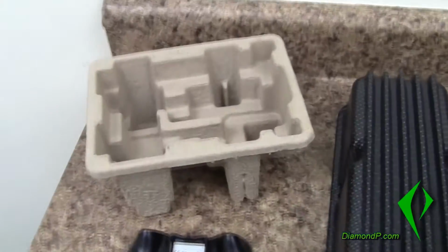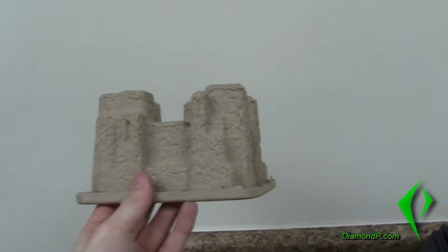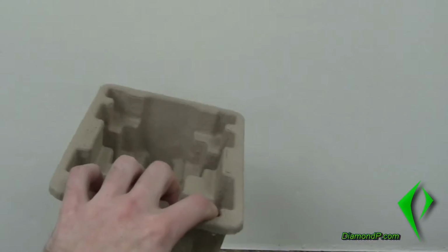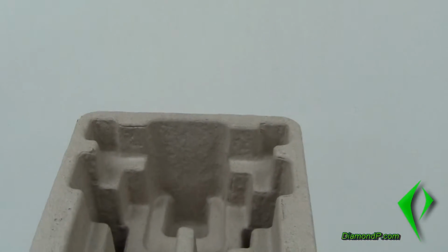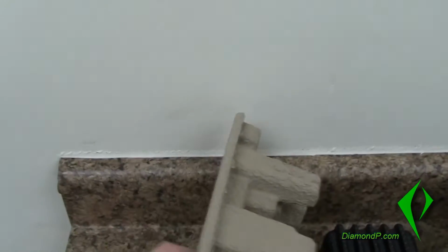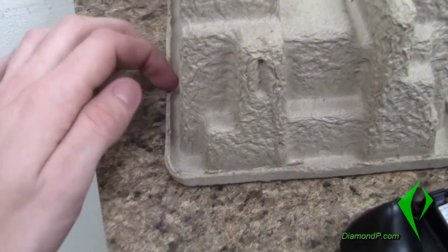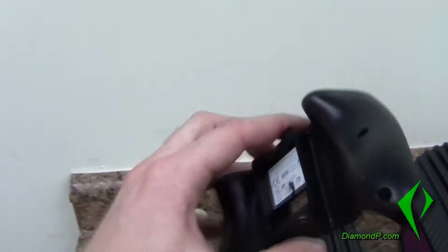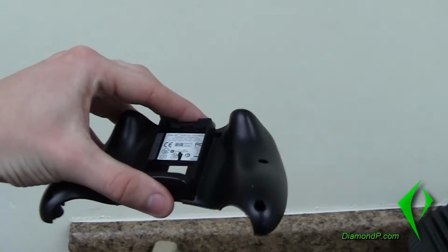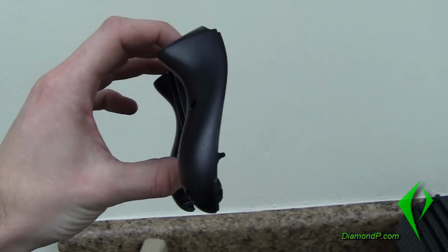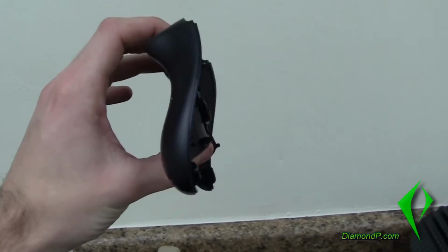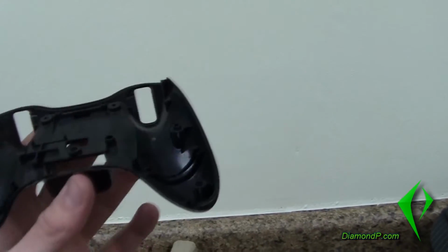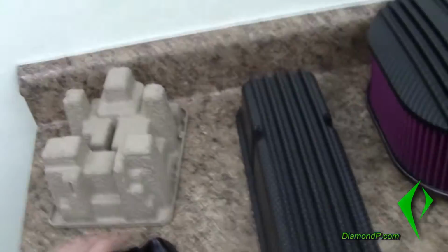Even this Xbox controller and cardboard box have draft on them because they were made in a mold. You can see the angles here, and they're angled on the inside, and the parting line for this is right here. Same for the Xbox controller. Everything is drafted, and this is a bit more complex. This is not a flat plane parting line. It's contoured all the way around the outside of the mold, so I won't talk about that too much.